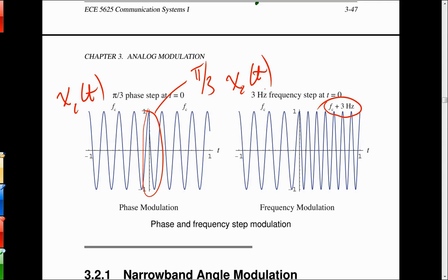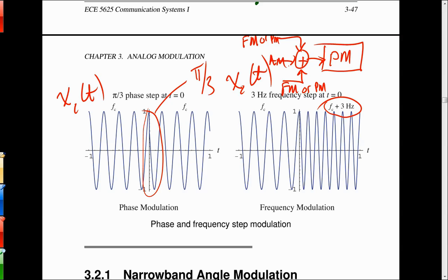multiplexing, and it is possible to multiplex things together. It's actually possible to take one PM modulator and sum together a whole bunch of different signals, and you can actually put FM or PM on a subcarrier, and then put FM or PM on another subcarrier, and then put, say, AM on another one still, and still have another one at baseband.